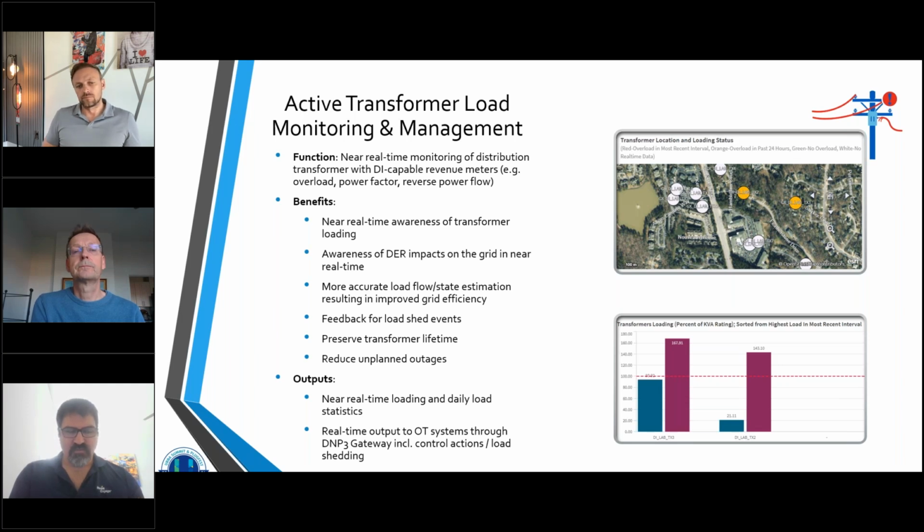So you're effectively getting every minute your demand, your active energy, reactive energy, power factor, min, max, and average voltage. So you're effectively touching every single device in the system every minute, with the ability to put control constraints relative to reporting by exception. So if you exceed load values or you exceed voltage values, you can alarm and push that data back, which